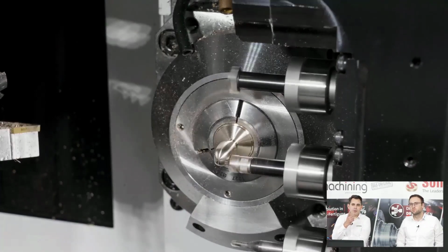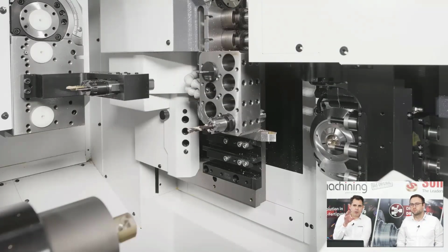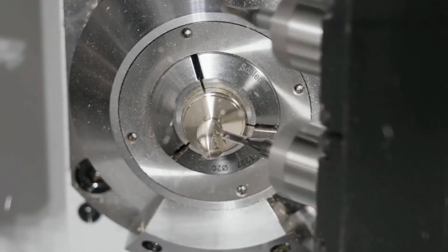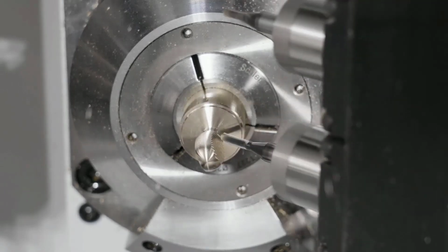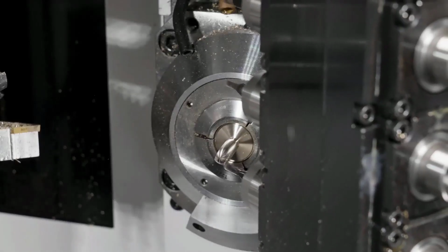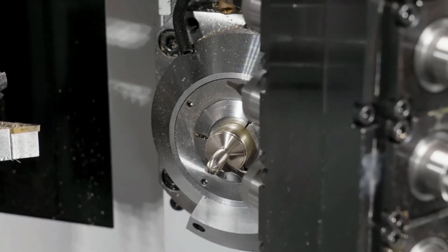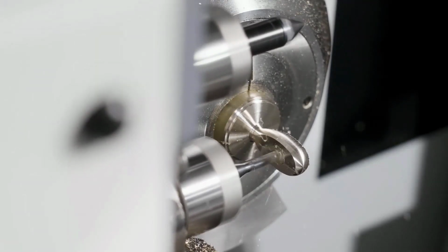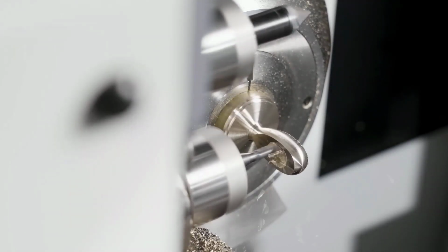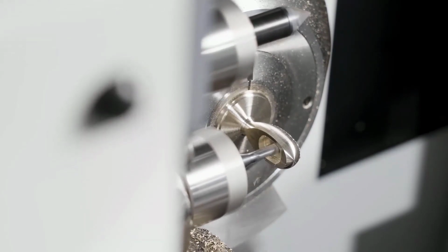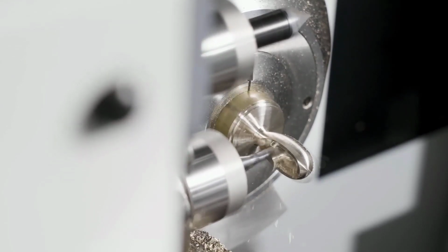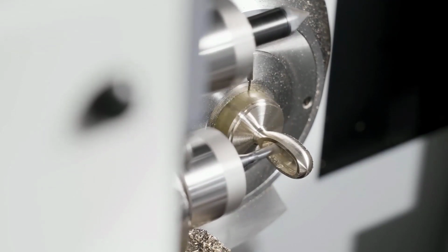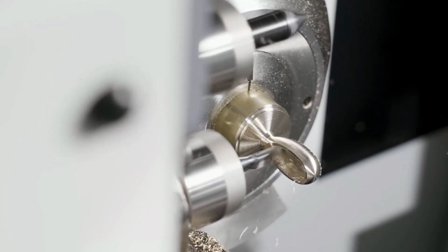Yeah. Maybe at this stage it is also important to mention that we are working now with the machine as a Swiss type with a guide bush. We can see the material is sliding. We can also modify the D25 to a fixed head. It means we will take the guide bush out and work with the main spindle directly in the work area. The benefits are basically two: we can reduce the remnant part. It means this is also money. If you are producing from expensive material, you can reduce the rest of the bar to the minimum. And the next benefit is you can use material with less quality, with H11 for example.